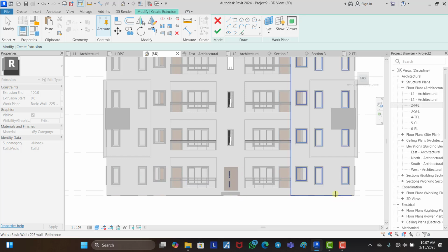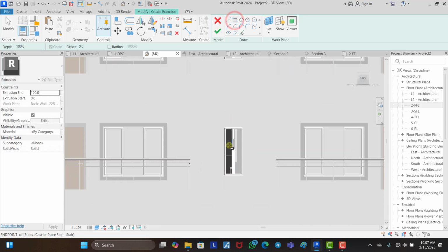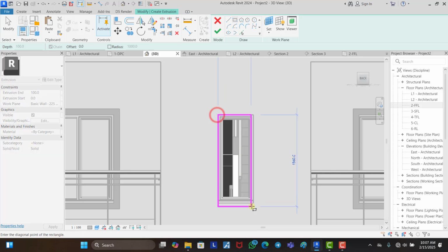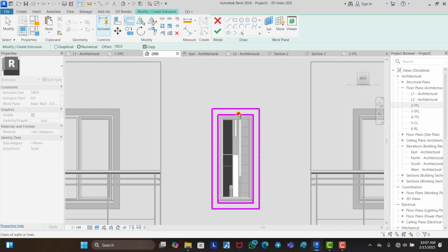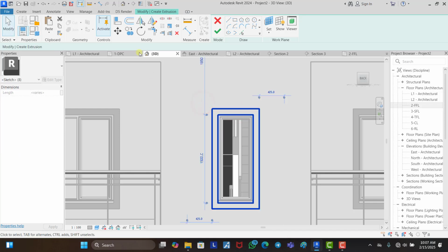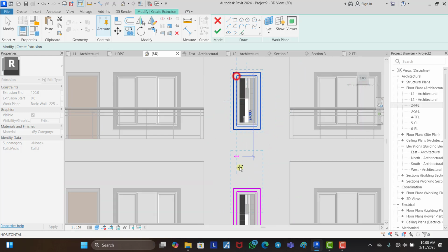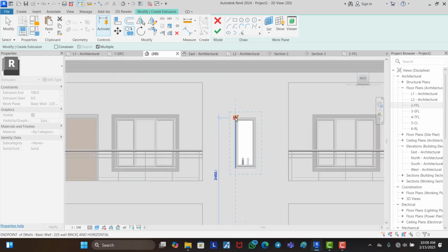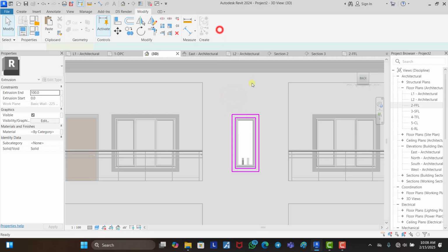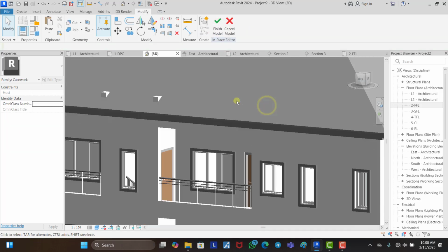Okay, we can pick this wall, yes, because it's the same thing with this wall. It's good. So we can use this wall. Perfect. Offset 100 mm all through. Select, copy from here, go up to this point, and also go up to this point. Perfect. So you click on finish and you have your window hood.